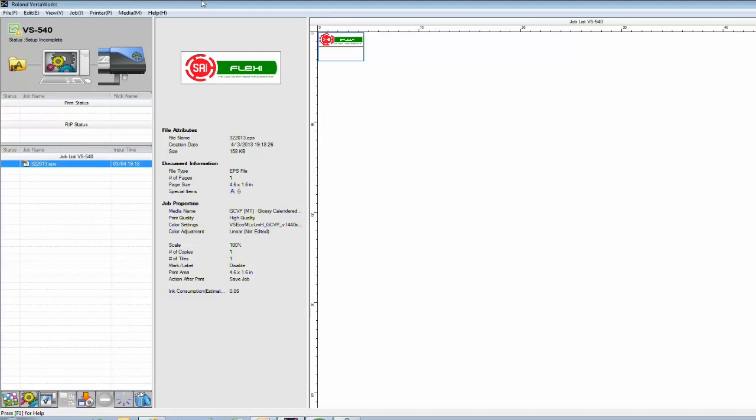For the basic queue setup, most of our clients set up QA for your standard print-cut option using their most common vinyl products. In order to start changing some of these settings, we go up to the Edit menu, and here you can change your QA settings, QB settings, and so forth. QB, at least for the clients that we have, is normally set up either for banners or an additional product that they use quite a bit, or as a cut-only option.